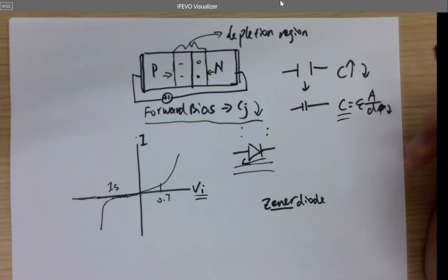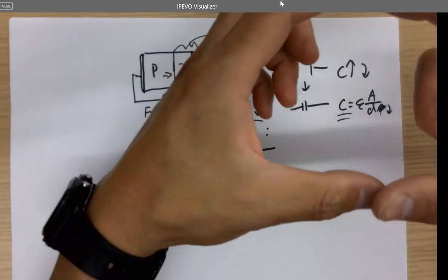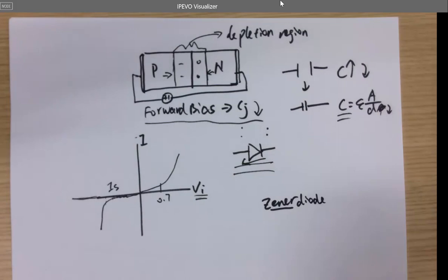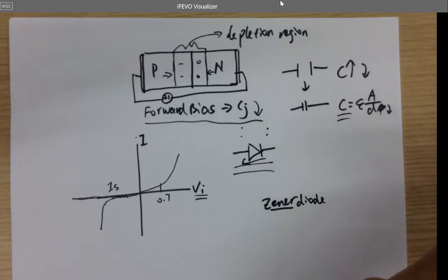Maybe if you show that little PCB to whoever interviews you for the job, they will ask why you used a Zener diode over there. So this is a power supply module, I use it as a regular diode. It's ridiculous. Don't do that. It's not like I found a diode, so I'm going to use it. You have to look at the data sheet, see if that fits the circuit board.